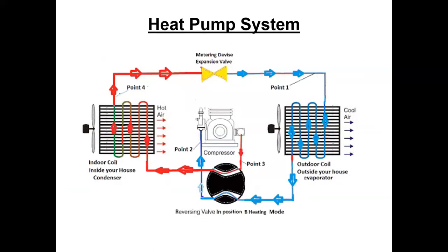Now, our reversing valve has rotated, right? So look, the flow's in the opposite direction across the expansion valve. It was going the other way before.